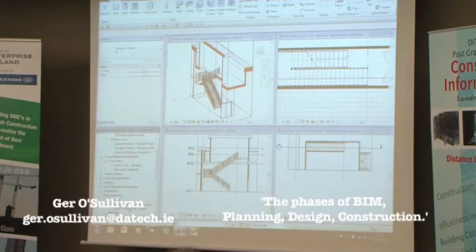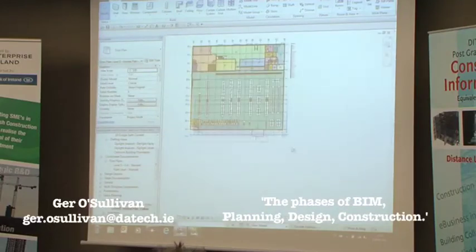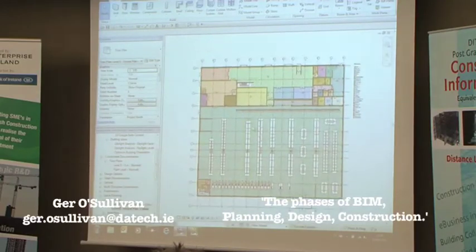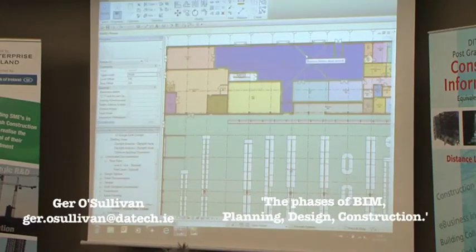So we'll have a look at the format color here. And something like this, okay? So what we've done here is we've added in rooms to each of the spaces, we call them. So as you can see, if I selected that area there, it's telling me it's a room, bulk store 8. If I select it, I'll just move down to the overall information like areas, perimeter, unbounded height, volume for that room, name, number, that type of thing, department even.